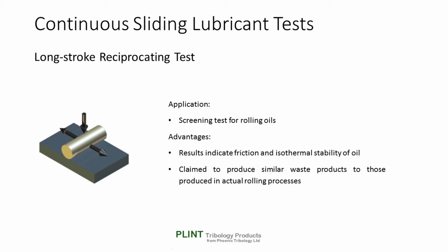To simulate the behavior of additive packages over a range of temperatures, reciprocating tests are run using a plate sample of sheet material, the material to be rolled, and a hard moving counterbody representing the roll, with stepwise increasing temperatures. Tests have been performed with steel, zinc, copper and aluminium workpieces.